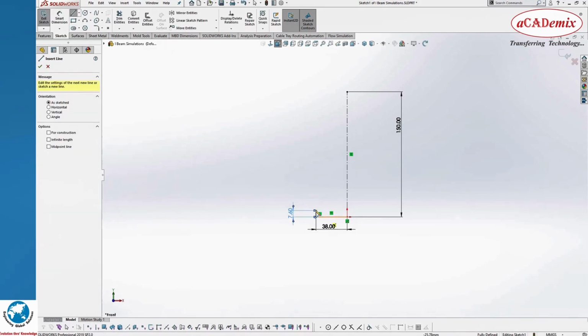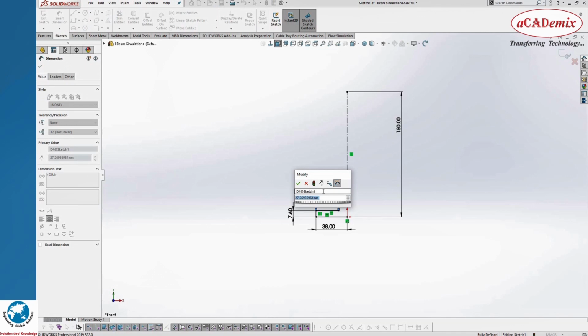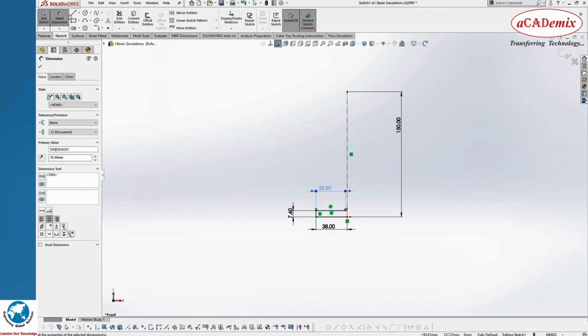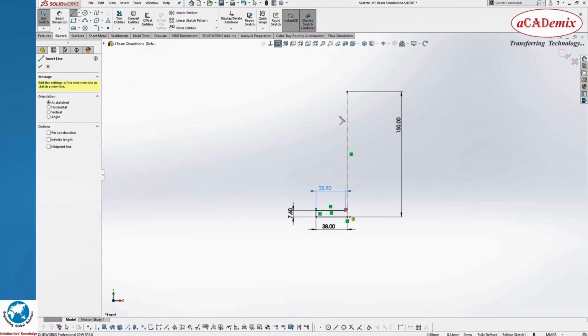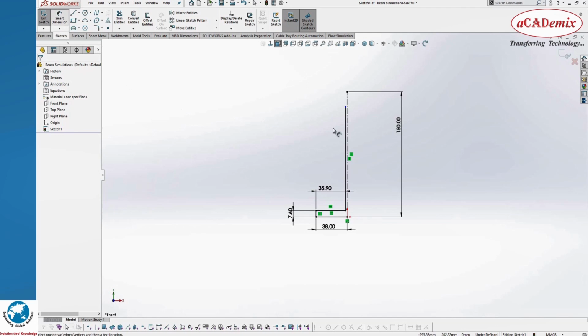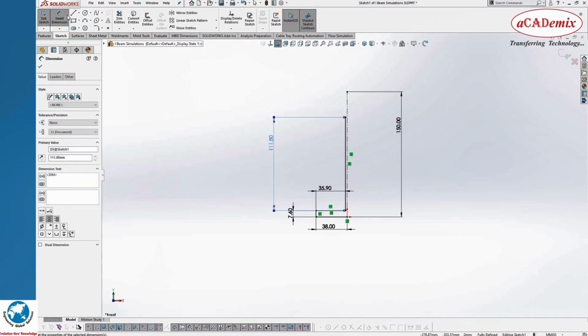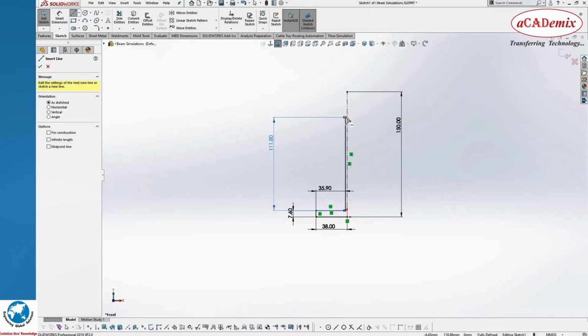Here both the bottom flange and top flange of the I-beam are symmetric. That is, both the top flange and the bottom flange have similar dimensions. The overall depth of the I-beam is 127 mm and the depth of the web itself is 111.8 mm. Next, we are going to model the top flange.